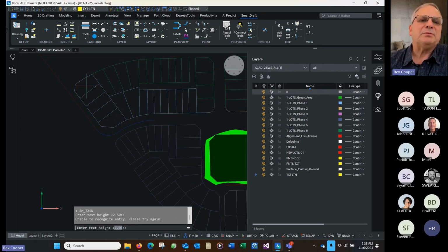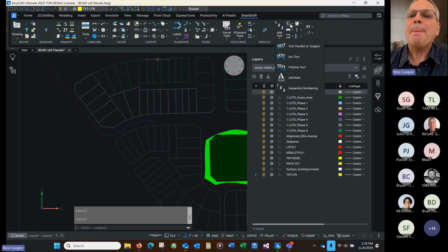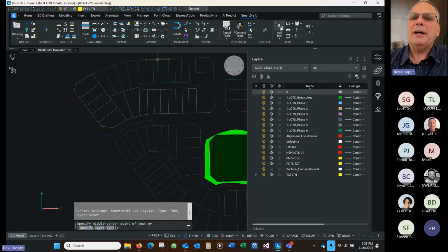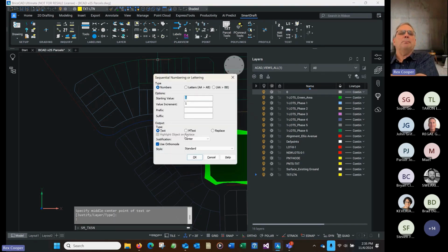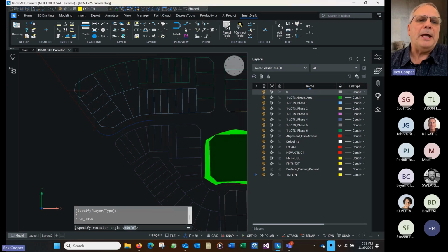and I'm just going to place, I'm going to first come over here. Sorry about that. If you look at my notes, I want to create a lot number, and then I want to do this. So I just picked a command that you can define that says lot numbers go on this layer and they use this font. And I want to have the justification center. I can have it M-text if you prefer M-text, or you can just have it regular text, depending on which one you prefer. You go and find the style that you want to use.